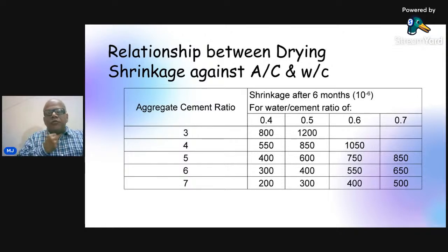What is the actual requirement of your cement? If you don't have to do any mixing, everything is taken care of, then at the minimum, how much water will the cement need for the chemical development, for the hydration of cement? Tell me, what is the chemical requirement of cement for water? How much water to cement ratio? Normally we use 0.4, around that, right? In our ready mix plants, in site mix concrete, maybe sometimes 0.48, 0.5, it is really bad concrete. So that is our range. Good concrete mixes are 0.35, 0.3.